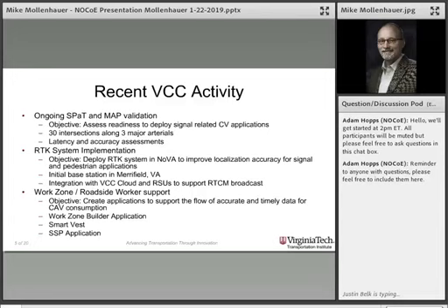We've also deployed the GPS RTK correction system. Within that northern region operations, there was not an RTK system or a base station that we could tap into for public use. So we went ahead and deployed our own base station in the area, and we are taking in those corrections. The base station itself is mounted on a traffic cabinet at an intersection, and we are taking that data into the cloud and being able to broadcast it.